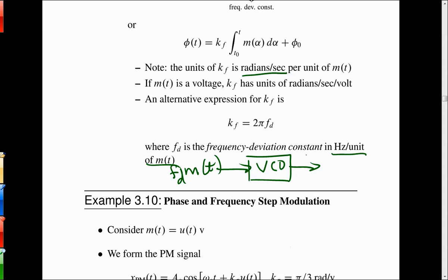Constant envelope signals can get amplified even by nonlinear devices, and it doesn't alter the modulation. It does produce harmonics of the carrier and so on that you might have to take out with a filter, but it has some nice properties for processing these types of signals, say in satellite communications, where you want to run the amplifier close to being in distortion, but you don't, and you want to have a very efficient amplifier, kind of like the class D, but not to that same extreme. It's more of a class C kind of an amplifier.